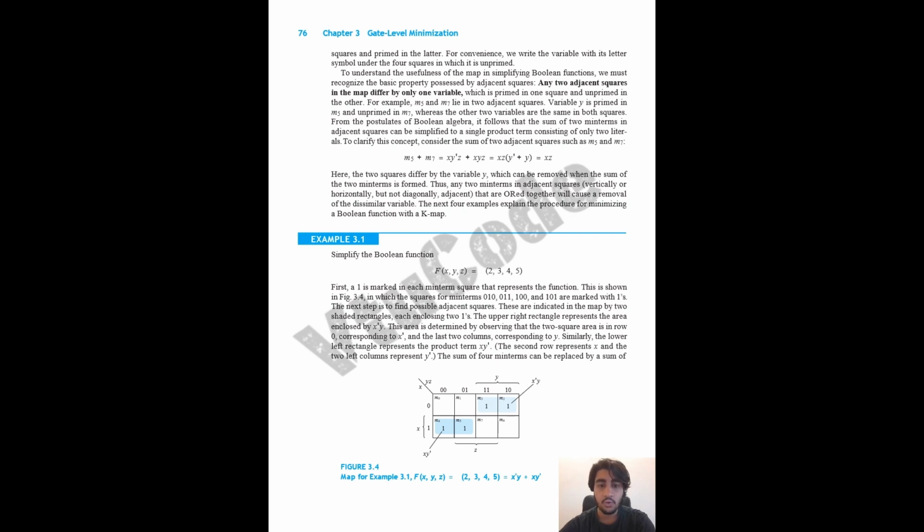So similarly, as I have told, 2 to the power of n, 2 to the power of 3 here for 3 variable is 8. So we have 4 plus 4 equal to 8 number of cells or squares. xy represented here. Similarly, we have the binary notation here as well as here. Now let us try to understand what is gray coding. In gray coding, the second and the third term gets interchanged. So, beg your pardon, it's the third and the fourth term. So we start here 1, 2, 3 and 4.